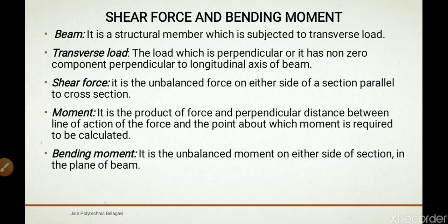How? When you apply the force with the help of the handle, right? So you're pulling or pushing the door and it is rotating about the hinges, right? So the force which is applied on the handle is perpendicular to the door, and that is the perpendicular distance from hinge to handle, right? So the product of force and perpendicular distance can be said to be a moment.